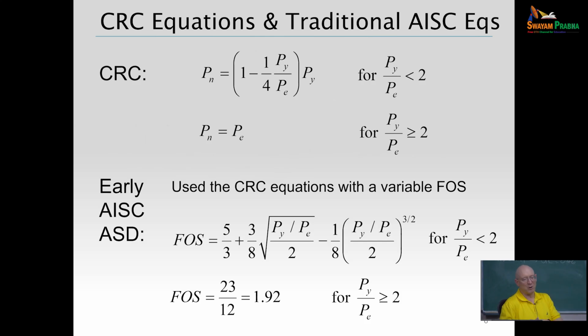So just to show you a few things, the old CRC curve was the formula you see at the top of the screen here, a very simplistic formula. It's based on a tangent stiffness model, just saying straight column, residual stresses in it, I get some reduction in stiffness as I load it up. Okay, what's the strength of that thing?